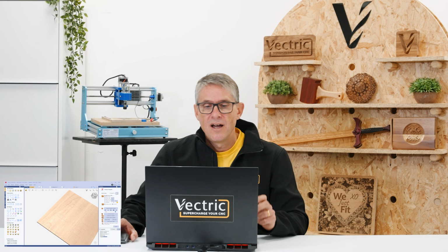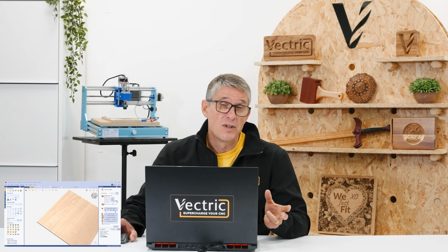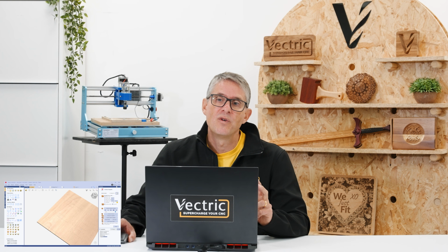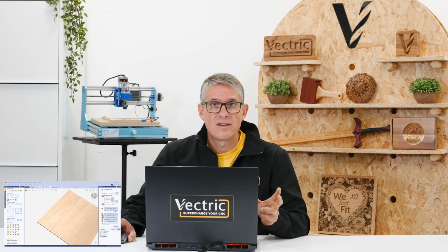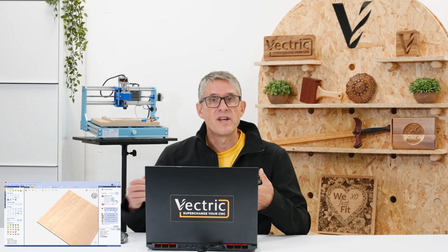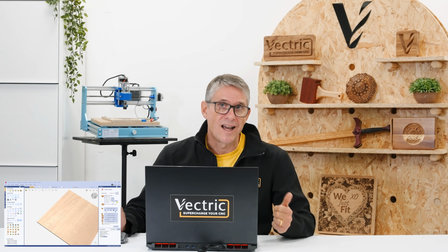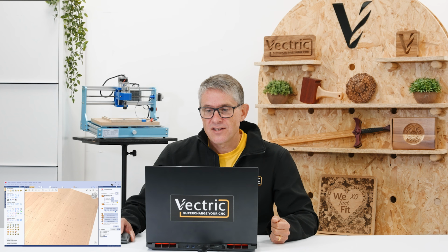Another thing to mention at this point is for those people with controllers that can have cutter compensation on profiling. So if you're a business that's keeping track of tool wear and tear, or maybe you've got a tool change with fixed standard tool sets in, and sometimes you use the controller to correct for a slightly mismatched tool diameter using cutter compensation, we can now support that with the post processor, and again in the advanced machining module when you're doing profiling. So this, like I say, is a new module.